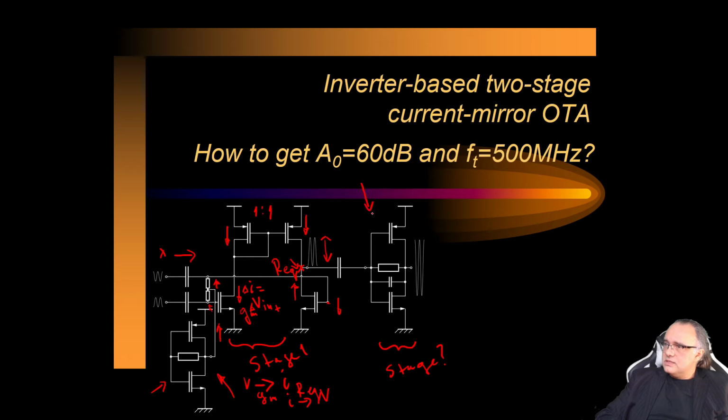In this case, the other stage is first of all again DC decoupled, AC coupled. So we block the DC component, because the common mode of the signal here, the biasing point, is not necessarily optimal for the second stage input. This is why we decouple for AC signals the input stage and the output stage. The biasing for the second stage is realized by this resistor, a self-biasing approach. In this way, we guarantee that the transistors of the second stage will be biased at an almost optimal operation point.